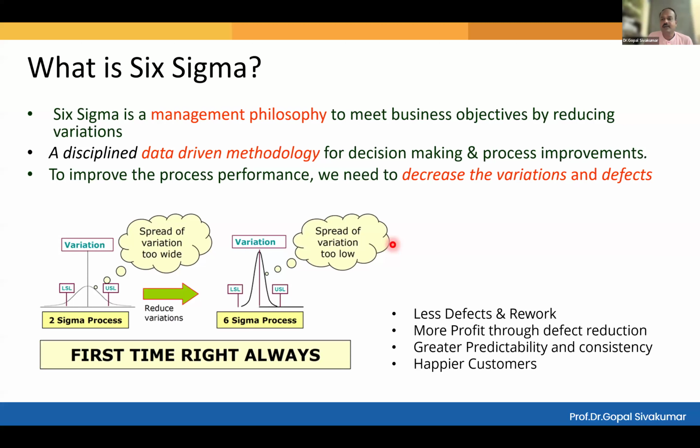I suggest all of you to even read some literature about normal distribution, because the theory has been developed after a lot of research. Specification limits are predefined, but the control limits are how to take in. Control limits, I told you: you have to find out the point which is 3 standard deviation away from the center.